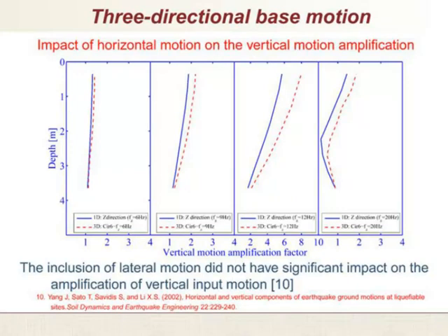These are the different amplification factors for different directions, and the conclusion here is that the inclusion of lateral motion did not have significant impact on the amplification of the vertical input motion.